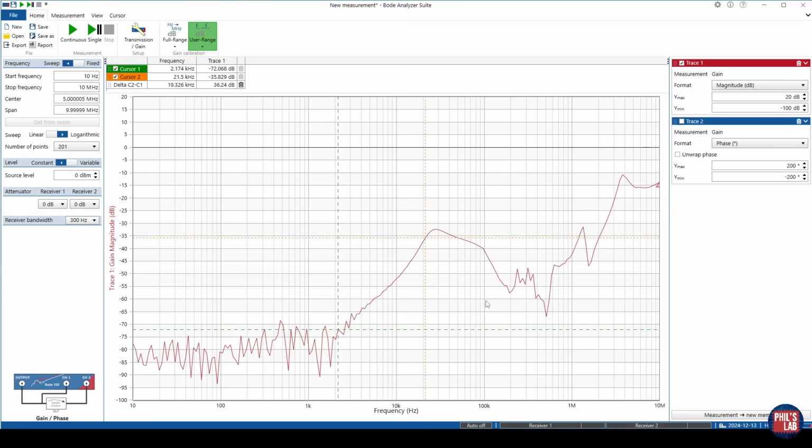Also, these peaks and dips are due to, of course, the regulator itself, but also due to the surrounding circuitry. For example, input-output capacitors. Depending on what type those capacitors are, and the interconnects, you will get different peaks and dips. And this, of course, also depends lastly on the operating point, so our input voltage, output voltage, type of regulator, and so on.